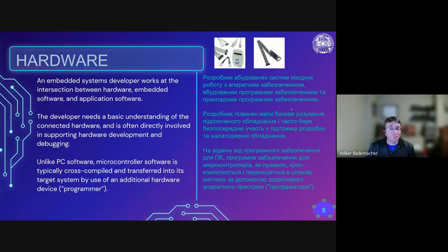Sometimes, if you're becoming more advanced, in particularly difficult circumstances, when debugging sporadic failures, it becomes a task of the firmware developer to debug hardware problems. Because you as a firmware developer will have the capability in your hands to log sporadic component failures. If you have a memory available, some kind of micro SD card that you can access, then you can log the data needed by the hardware designers to fix their hardware problem.